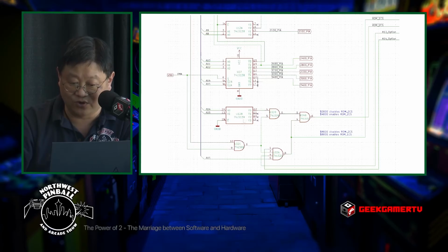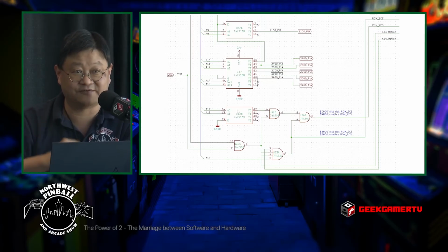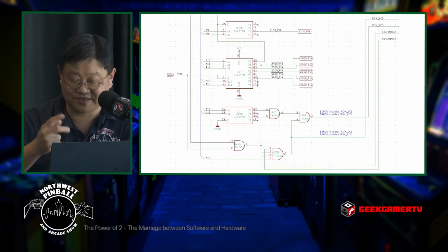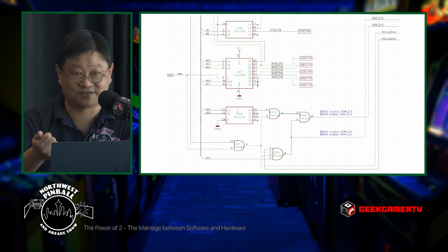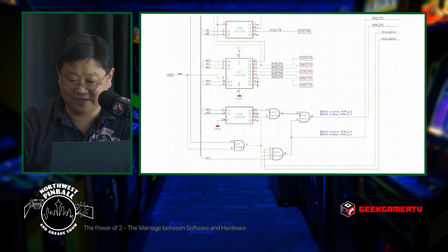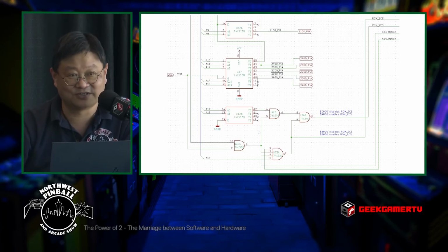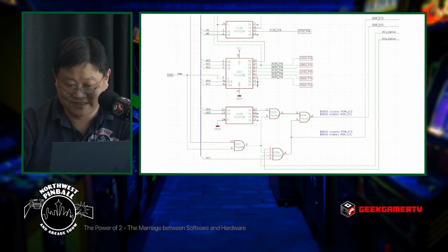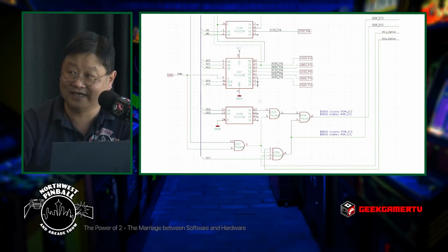So this chip is always looking at A14 and A15. And because there's 2 bits, you can either have 00, 01, 10, or 11. And guess what each of these 4 outputs correspond to? They correspond to either 0, 1, 2, or 3. And because of the way that I did this schematic symbol with that 45-degree angle line, that means the signal is active low.